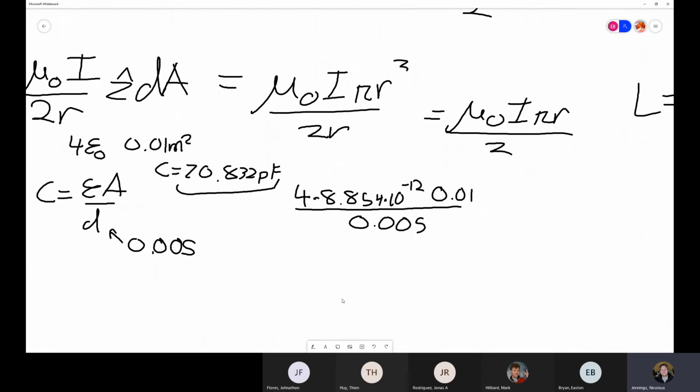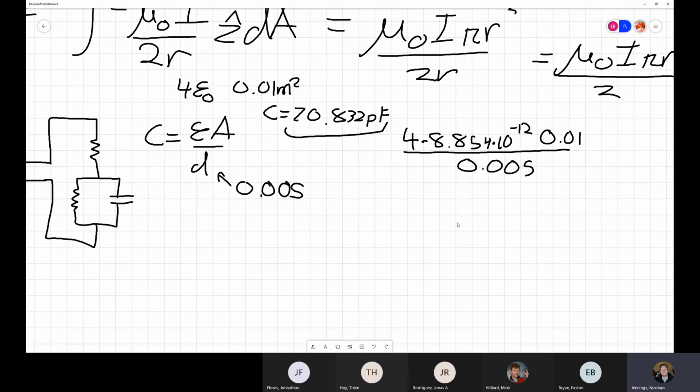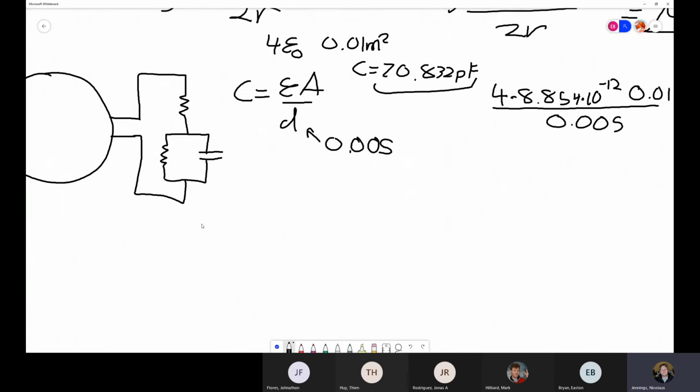Now what we have is, after solving for the capacitance, we then have to solve for the resistance. So remember the equation for the resistance. It gives it to you as conductance first, but of course it's just 1 over conductance. So R equivalent is then L over sigma area. L is of course the distance, I believe. It's the same thing as D. So I can just rewrite this as D over sigma A.